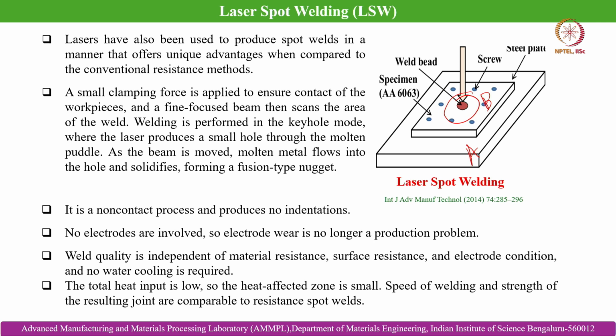That is why it is often a permanent defect that generally takes place in the parts which are experiencing joining. That kind of difficulty is not there in case of laser spot welding because of its highly localized nature, and so crater formation tendency is not there like arc welding.